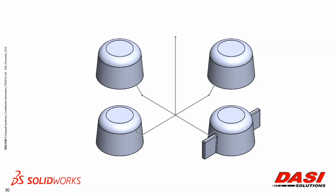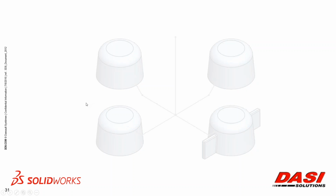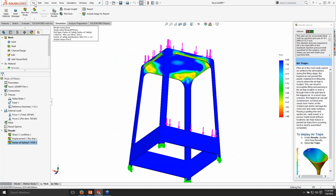So the example I'm going to show you is just 3 very similar parts, and then one that's a little bit different, has a couple extra features on it. If I were to use the same size runners leading up to all the parts, then you would guess that, of course, this one's going to take the longest to fill. It's got the most volume to fill. So my goal in the runner balancing scenario is to try to equalize when all these 3 items fill. So let me show the rough idea in SOLIDWORKS.